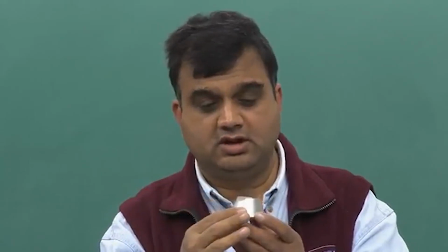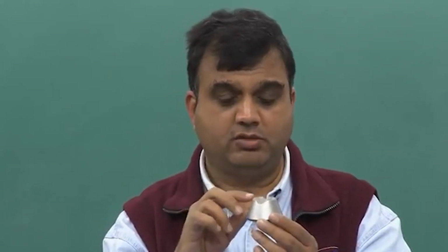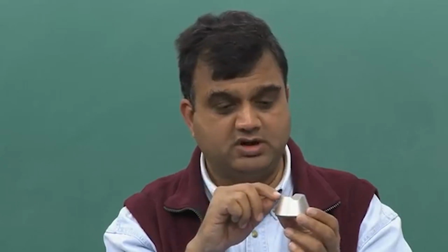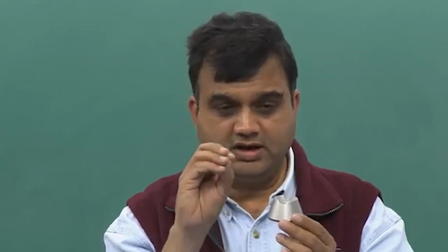But if I am using a numerical solution, then I will not have this kind of a formula, but rather I will have maybe at this point the stress is 3.1, at this point displacement is 2.7, so I will get numerical values. So the finite element method is a numerical approach.